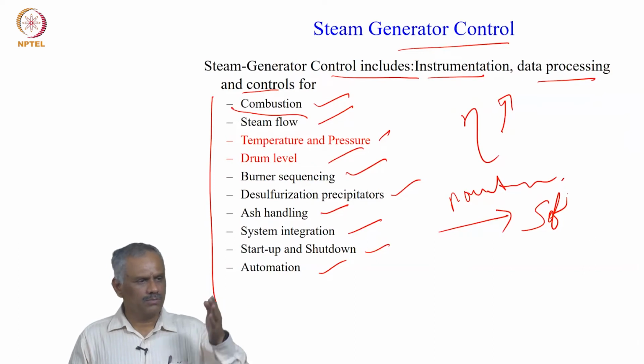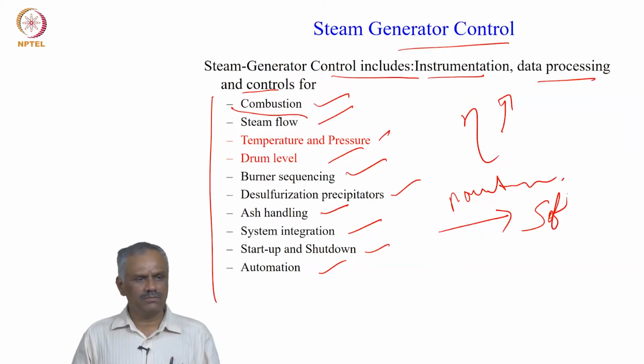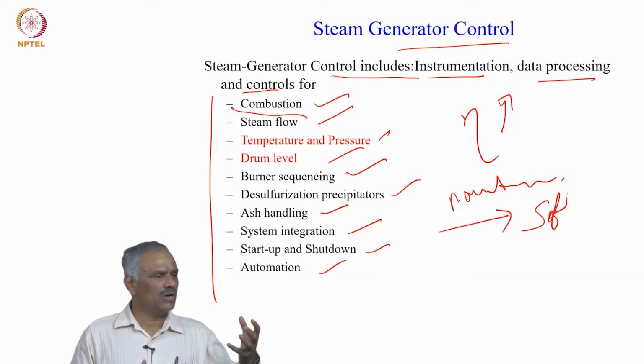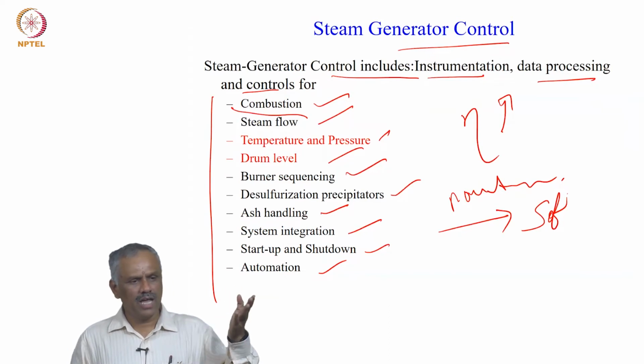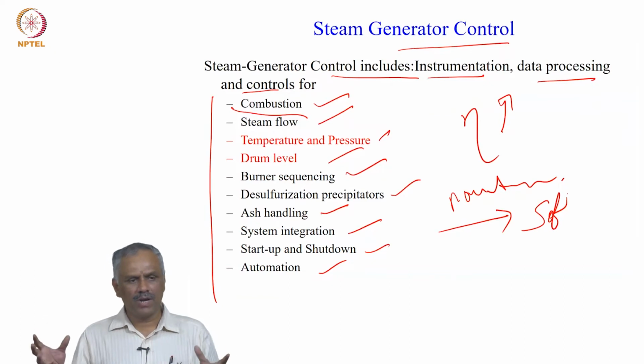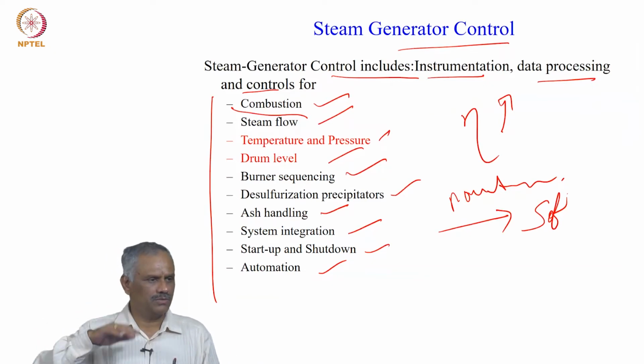You have to reduce the input, reduce the load, reduce the generation. So most of these power plants at off-peak, mainly daytime, when the solar generation is high, because solar you cannot produce in the night, whereas thermal power plants you can produce any time. So during the daytime the load is coming down. When the load comes down, these power plants have to be operated at part load operation, part load.